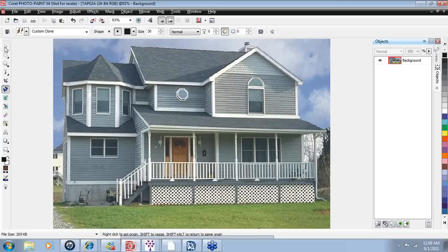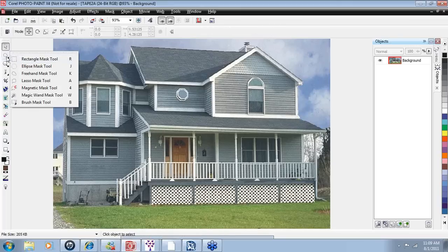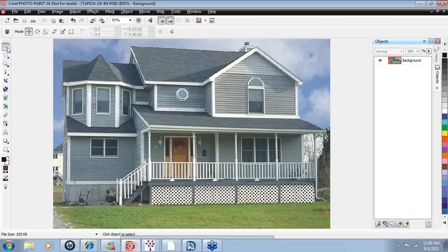Once items have been cleaned out, the next step or the process that I'd like to share with you is adding grass. So we are working with the left-hand side of our screen, the vertical toolbar. And if I place my cursor over top of any of these tools, you'll see that we do have a flyout indicating what that function does. And I'm selecting a masking tool. We'd like to mask off an area and add new grass. So I'm just simply left-clicking as I go to open up a mask line. You see this black and white line that's produced on my screen. And we want to fill this with a grass texture.